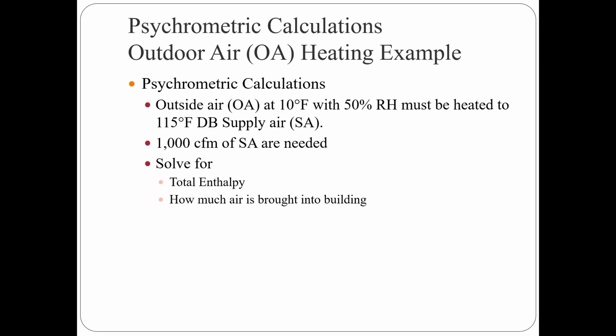So we need to figure out how much enthalpy or energy, enthalpy is just a fancy word for energy, how much energy we're going to need to put into that air to heat it up, and then how much air we're going to need to bring into the building from outside. So again, this is a pretty simple situation that as a mechanical engineer we would have to calculate when we were sizing a system for our building.